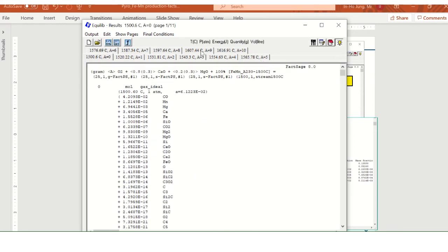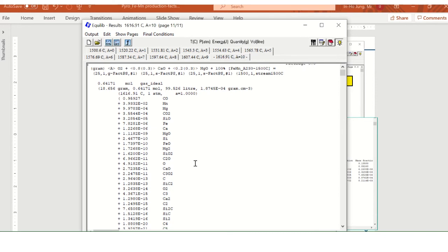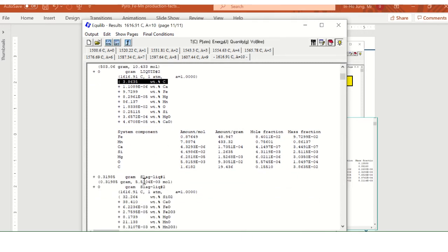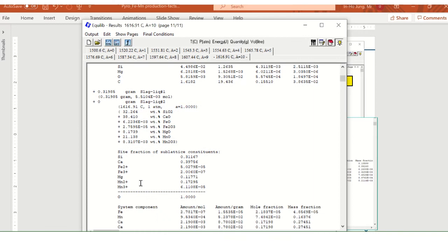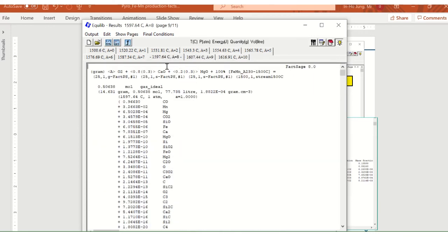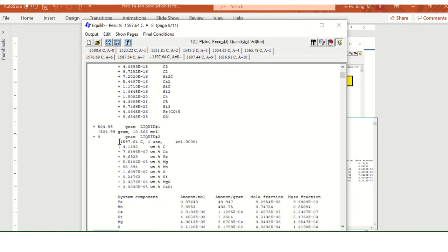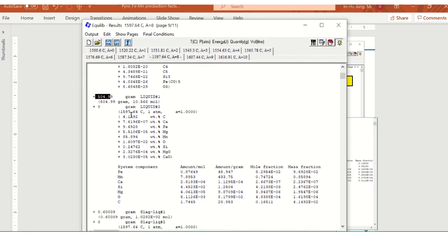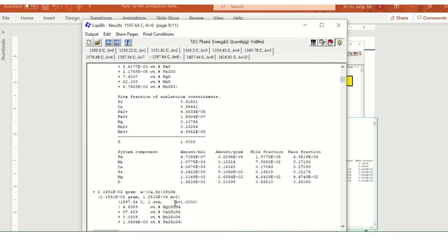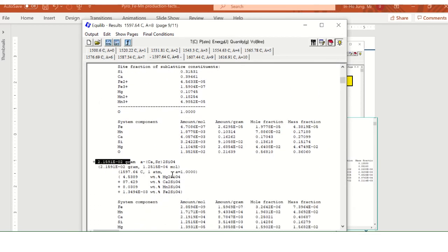And if you go to, for example, about 10, you see that some amount of CO is forming, and the carbon is still 3.8%, so it's very small. Then the liquid slag has started forming, and liquid solid has already started forming. And for example, if you go to 0.8, now about 500 grams of liquid metal is forming here, and the carbon is still very high. And the liquid slag is forming, and some solid has also started forming in the slag as well.